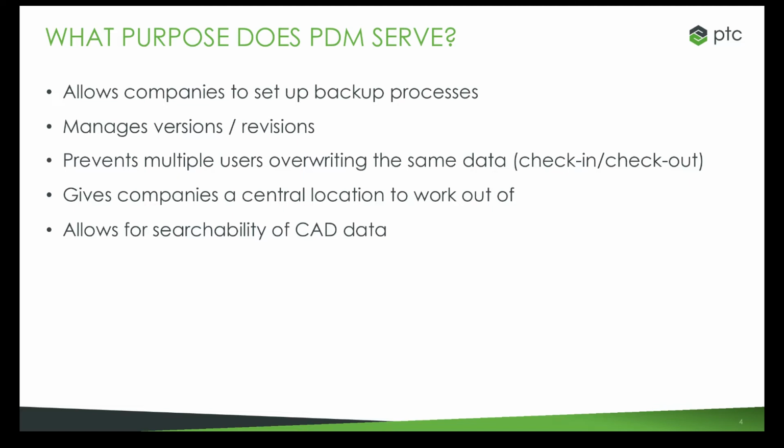What PDM allows you is a way to establish a check-in and check-out process, where when one engineer checks out a file, a design, they can make their edits and no one else can access the design until they check it back in. This gives you a way to prevent this sort of overwrite, to prevent conflicting changes.